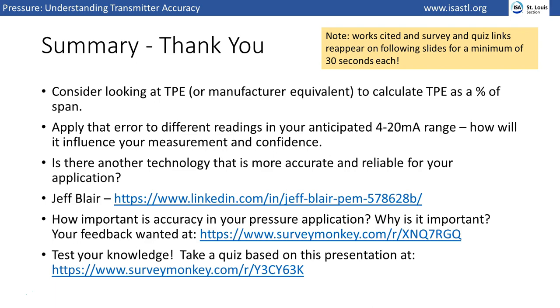This presentation was based on pressure transmitters. I used the hydrostatic level example, but we all know you could potentially use radar, buoyancy transmitters, ultrasonic level transmitters, point level switches. There are so many different technologies for each application.